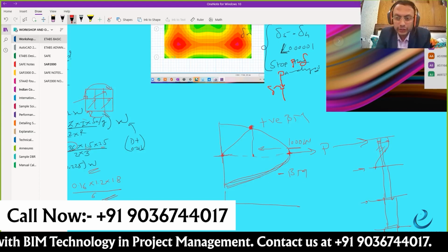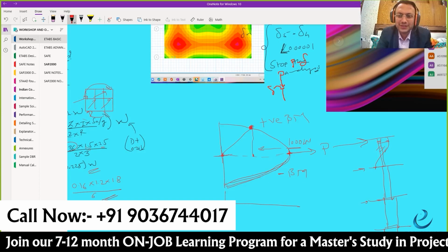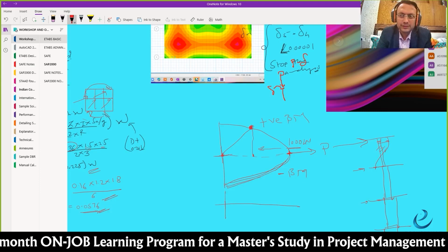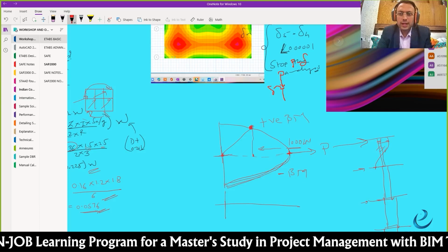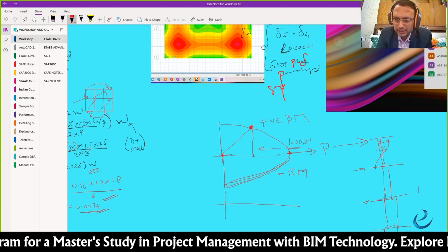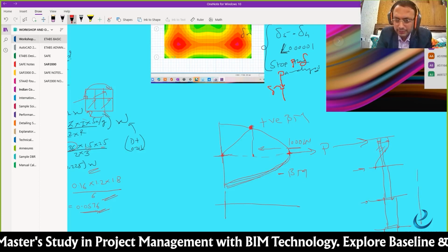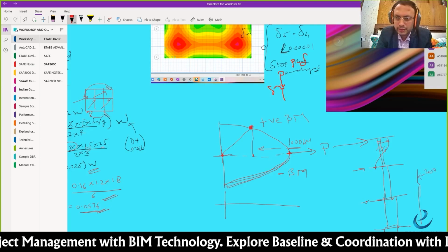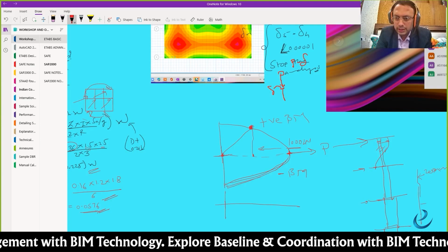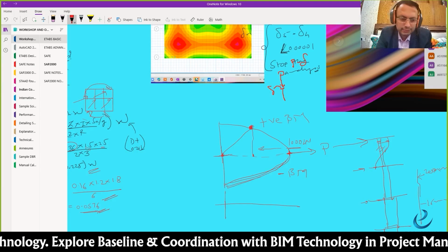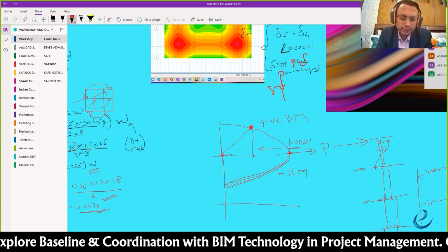But you cannot give the higher rebars on the top, so you need to take it from the bottom only. So we have to consider the maximum from the entire structure and then consider that. For example, if a 16 mm bar is there, you can lap a bar that is a little on the higher side, which is 20 mm, but you cannot lap 25 mm.